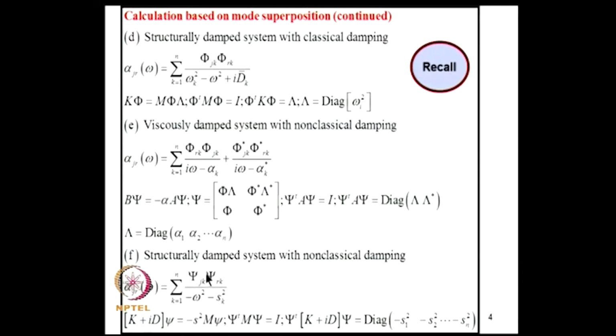In each of these cases there is a different interpretation for the natural coordinates, but the common feature is that there is an orthogonality relation satisfied by the modal matrices with respect to the structural matrices, which enables uncoupling of the equations of motion.